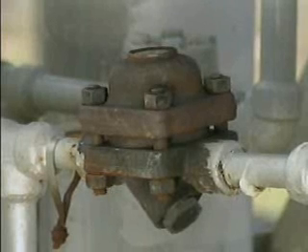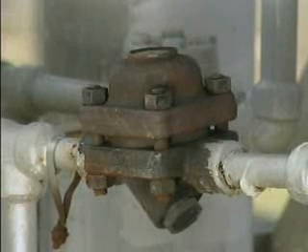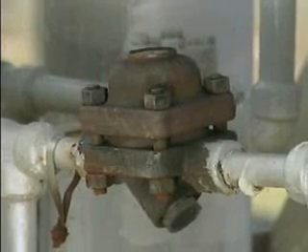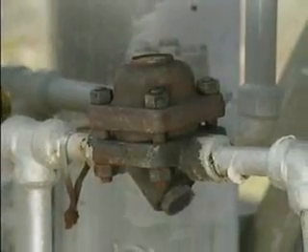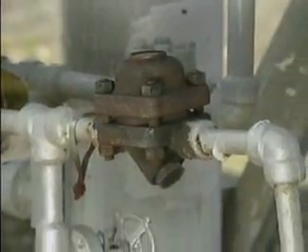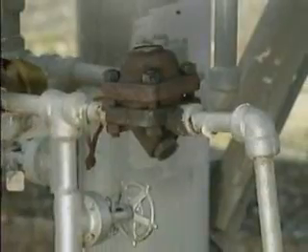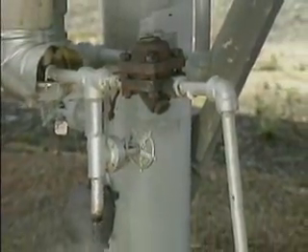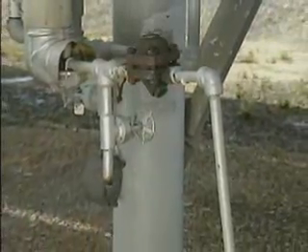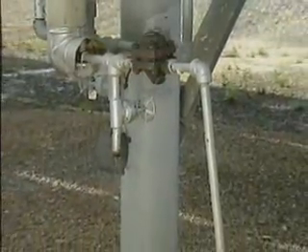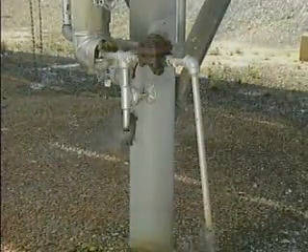Since the valve of a bimetallic trap is fully open when the trap is cold, this type of trap is effective during equipment startup because the trap can quickly eliminate air and cold condensate. But the trap response is more sluggish when steam has reached normal operating temperatures because time is required for the dissipation and absorption of heat that opens and closes the trap valve.